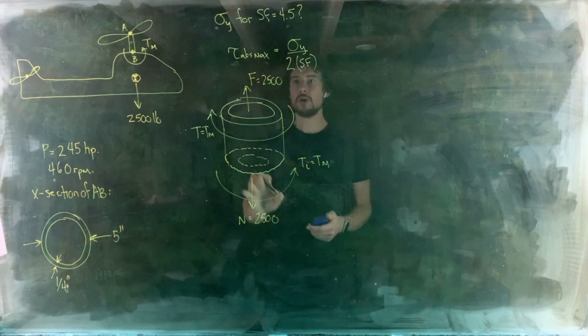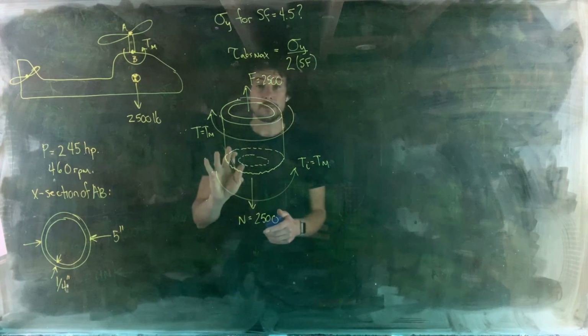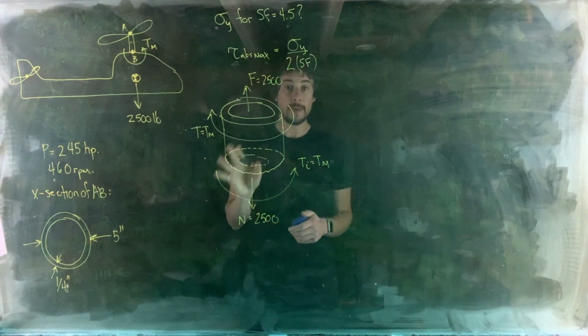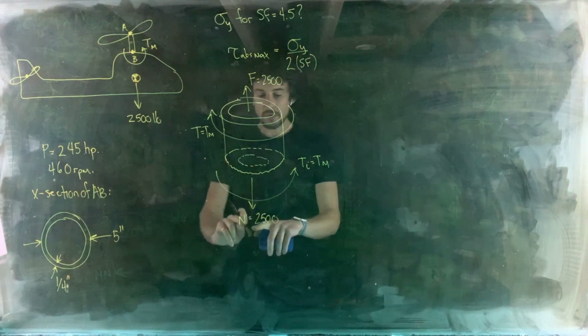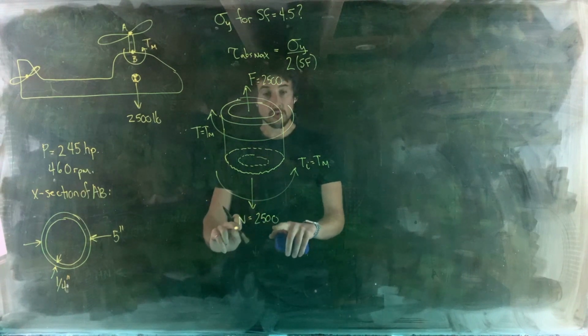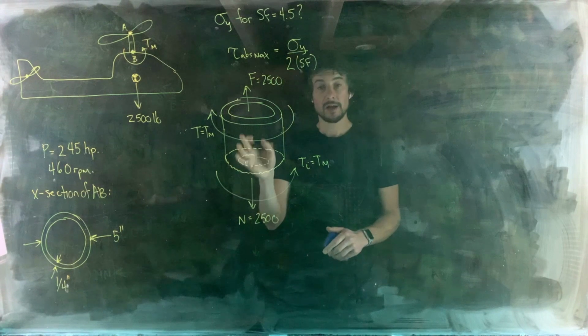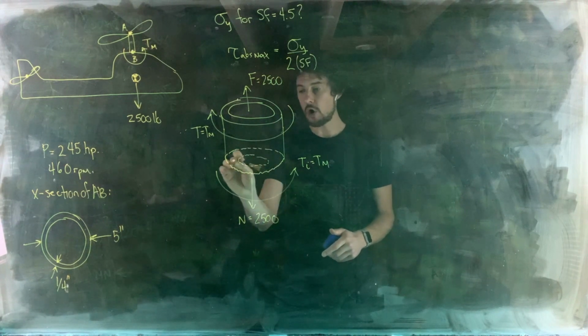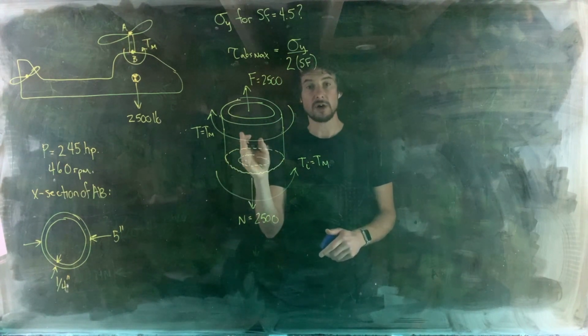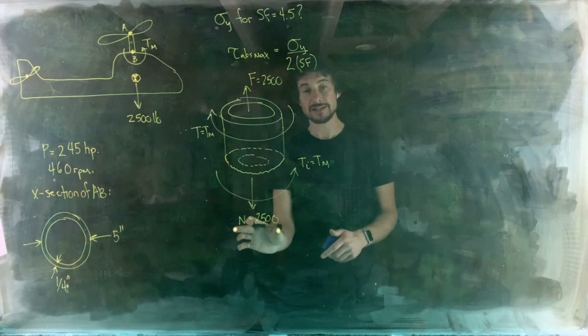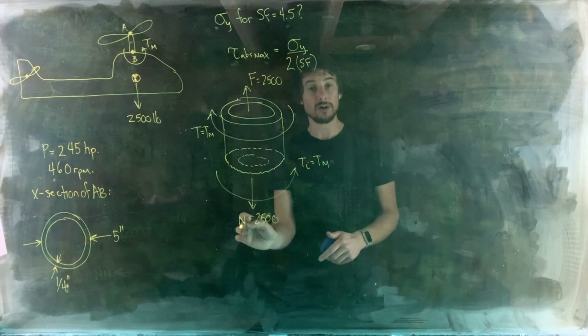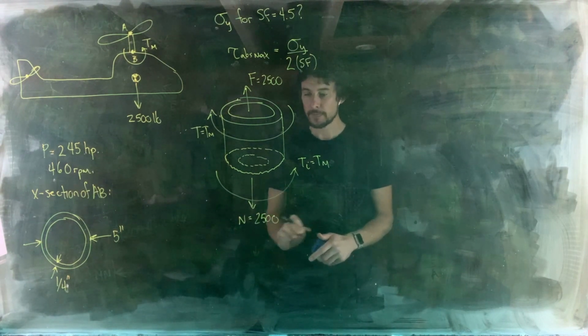Okay, so again, let's think about the point that is under maximum stress. From the internal normal force, that's a tensile internal normal force, so it'll create tensile normal stress. All points in the cross section are going to have that same tensile normal stress from our internal normal force, right?